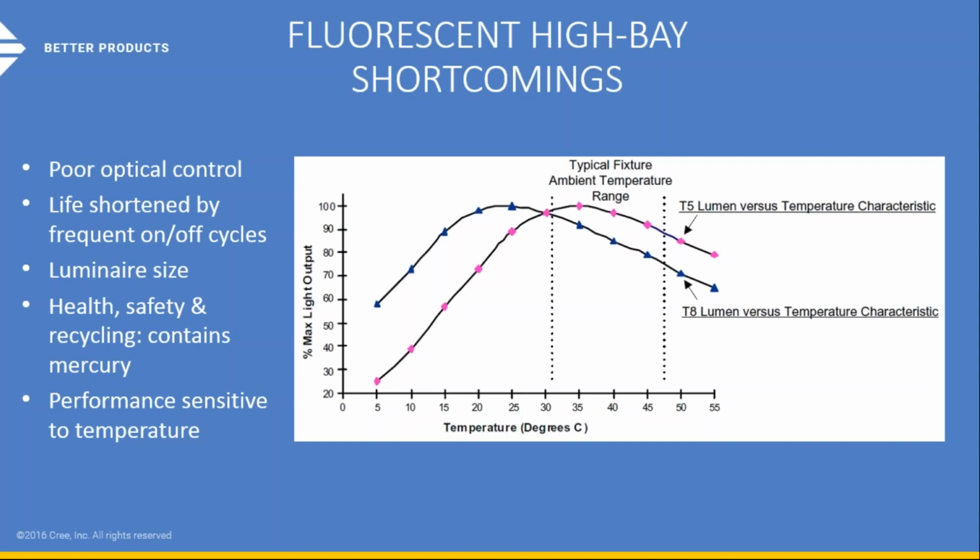Fluorescents are known to perform at a fairly high rate at low temperatures after warm-up. So if you look at the graph, I'm actually doing a click here, and you're going to see that optimal performance for a T8 32-watt linear lamp is around 32 degrees Celsius. The more improved T5 high output actually performs best at 35 degrees Celsius, actually at the warmer temperature.